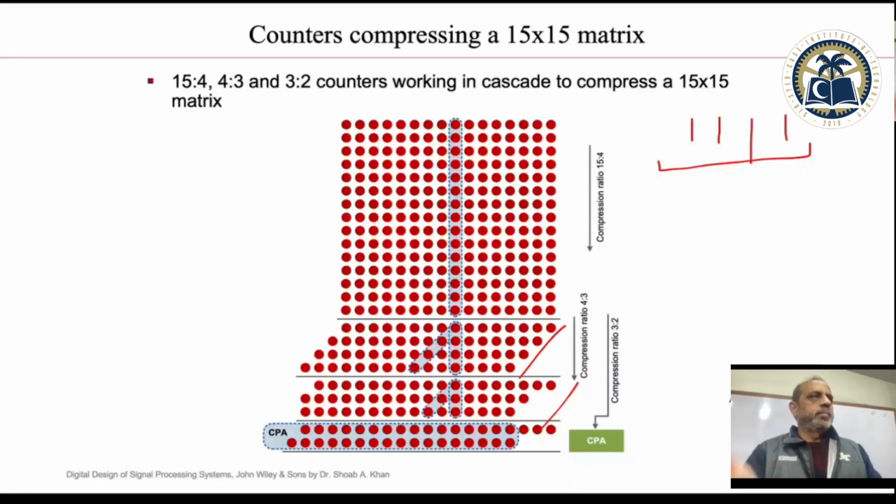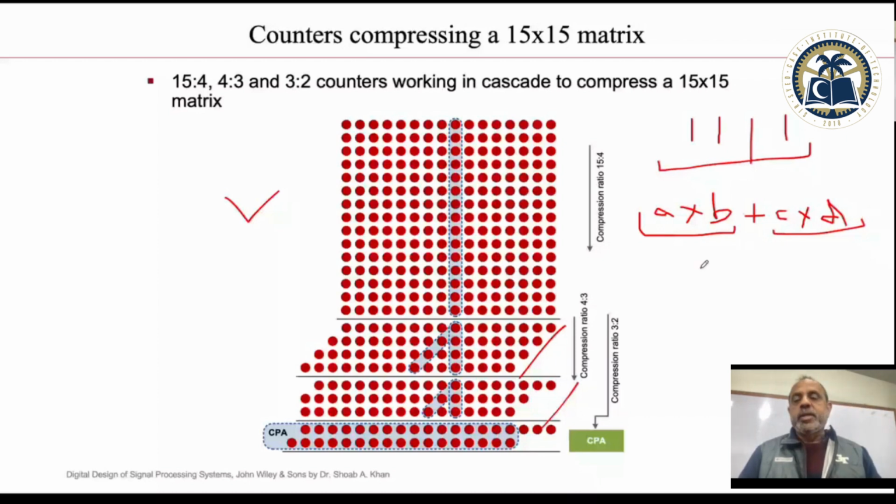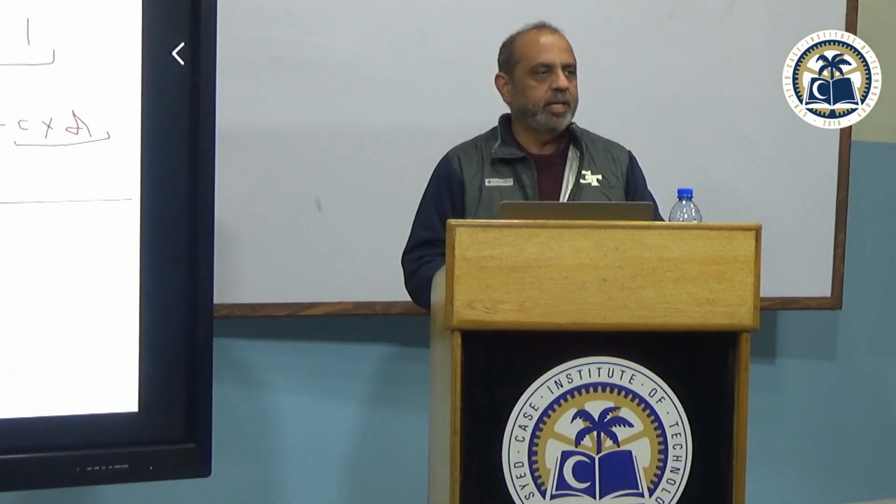And you will find many research paper publications which would, interestingly, in digital logic, say that even if you are multiplying, let's say A multiplied by B, like we do all the time in convolution and in correlations, and then you have, let's say, C multiplied by D, these are all partial products. Especially once you are doing filtering, you may have hundreds and thousands of partial products which you have to compress to find an answer. So in many algorithms, we never put a carry propagate adder.